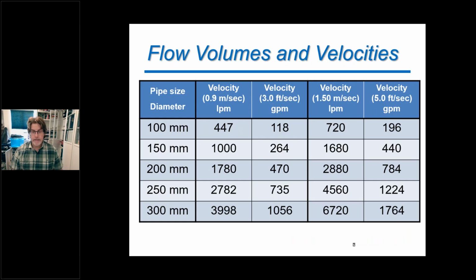if that was a 6-inch and we're using a 6-inch main that we are flushing, we look at the chart, it says, hey, I need to get at least 440 gallons per minute. I'm getting 650. Perfect.